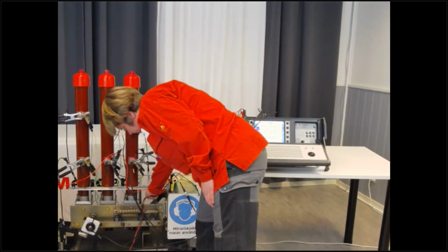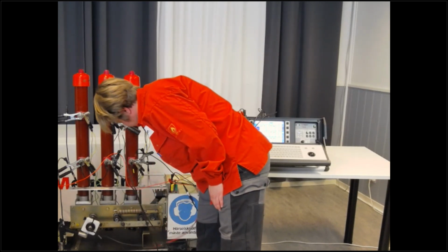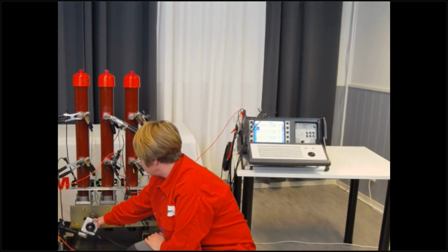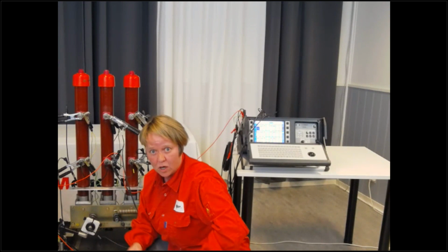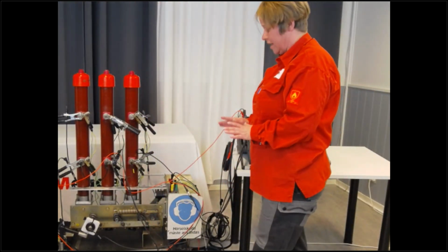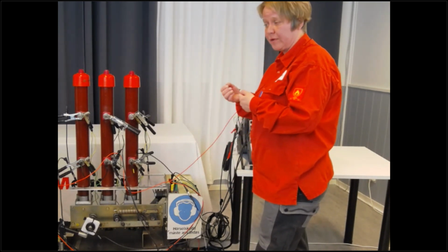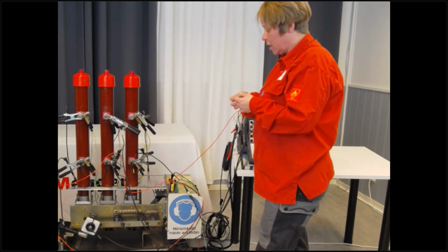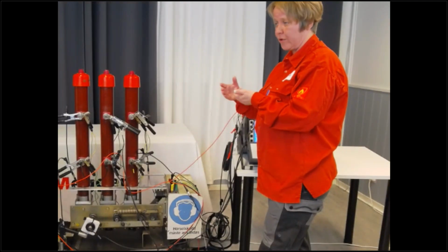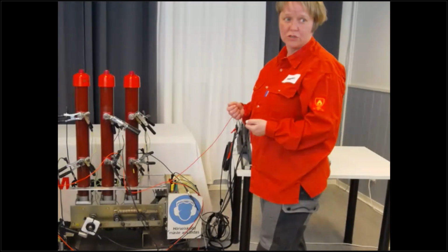sure that things are not coming into the mechanism here. Especially when you mount your motion transducer, it should not interfere with the mechanism of the circuit breaker. And if you're using a linear transducer, make sure you know which way the link arm is going, so you don't damage the transducer. Because if it tries to move outside its region, the physical impact can damage the transducer.